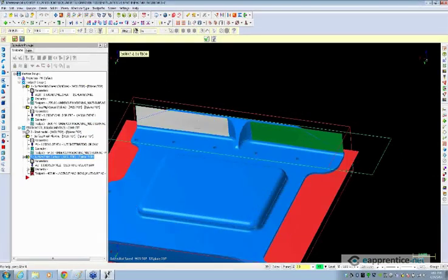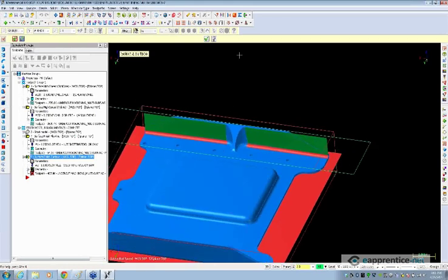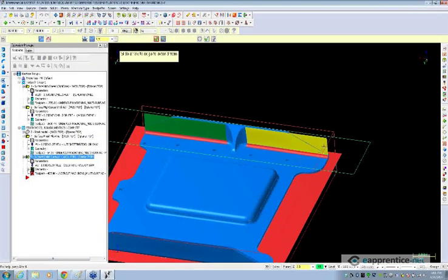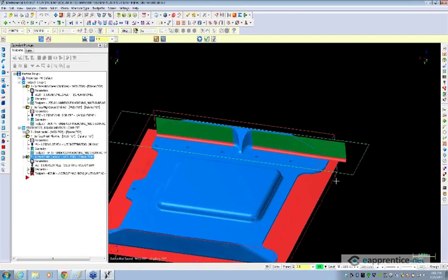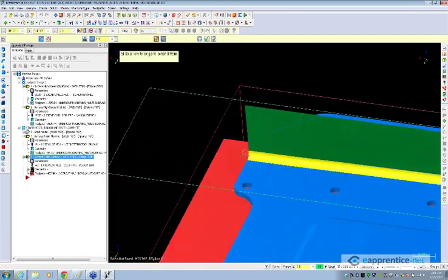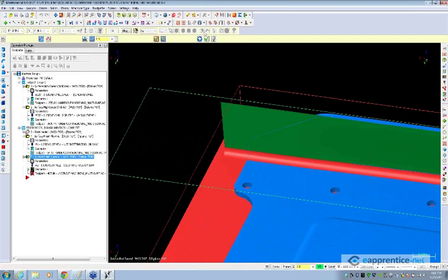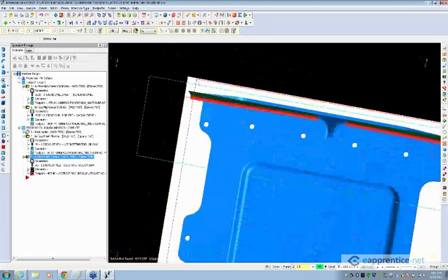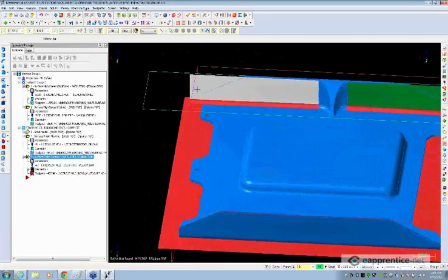So I'll untrim that surface and untrim that surface there. Okay, I may need to do it to these fillets down here as well. And now I can do create a surface, extend. Let's go 1 inch out that way. Okay, now, if I do that, I also need to be aware of how much extra I'm going to be cutting on that surface.